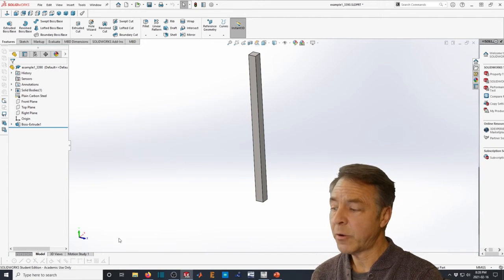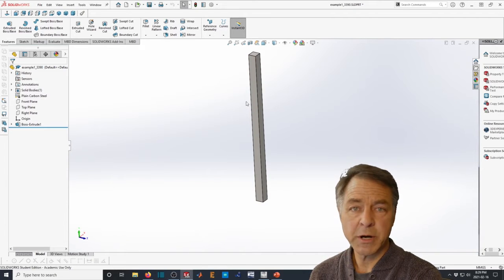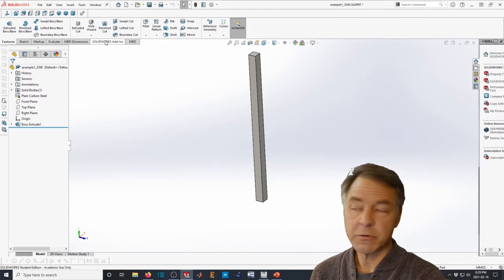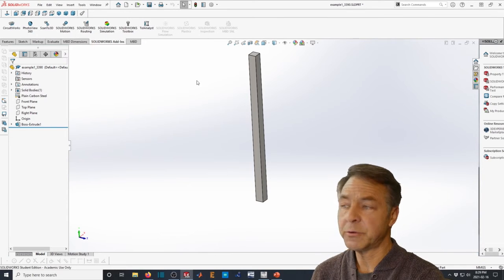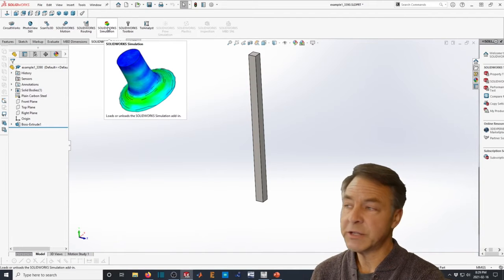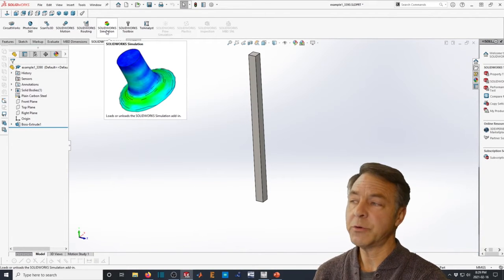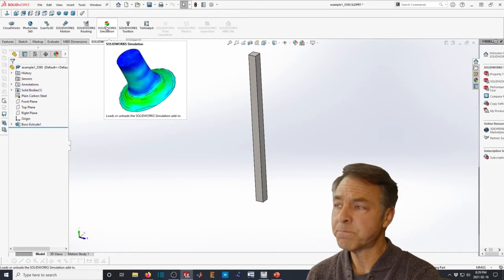starting point. Now, in SolidWorks, you'll see if you've made this in part mode that you should have a tab button here that is SolidWorks add-ins. And if you click that, you'll see there's a bunch of additional tools. You've probably played with some of them at this point already. One of them is simulation. Now, if this doesn't show up in your version of SolidWorks, go back to the installation for the licensing, and you can click a tool in the installation process that will add the simulation tool to your license. You have a valid license for it.